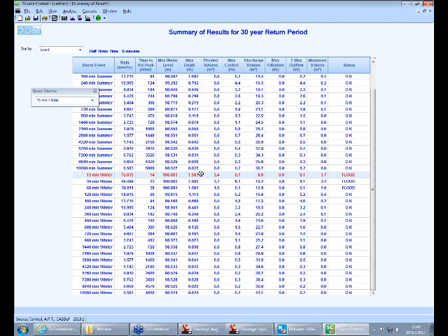First being flooded volume. So we can see we have a flooded volume at this location of 3.4 meters cubed. We've also added in the discharge volume. So leaving out of the orifice on our house soakaway, we have 8 meters cubed. You can see for some of the longer storms, we see a greater discharge. The one that's highlighted in red is the critical storm.